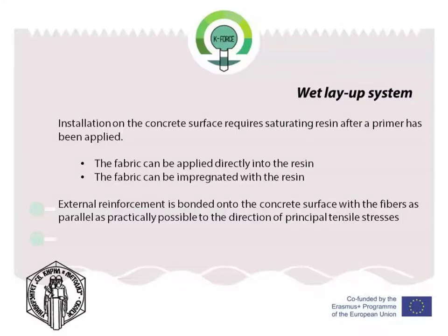Two different processes can be used to apply the fabrics. The fabric can be applied directly into the resin, which has been applied uniformly onto the concrete surface. The fabric can be impregnated with the resin in a machine and then applied wet to the sealed structure.